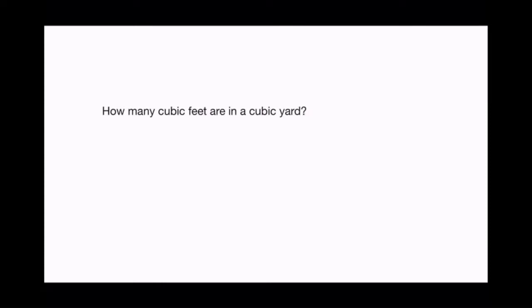The answer, of course, is 27, because a cubic yard is 3 feet by 3 feet by 3 feet. And so it's not 3 cubic feet in a cubic yard, it's 27 cubic feet in a cubic yard. It's a very no-duh statement, but if you're in an exam, it's very easy to mess it up, because it's quite likely that both in practice and in the exam, you're going to have to move back and forth between cubic feet and cubic yards, whether it be in concrete or fill.